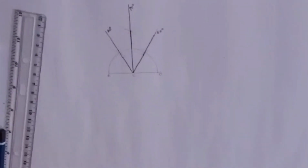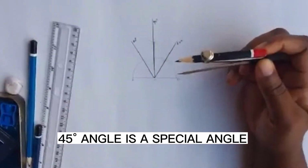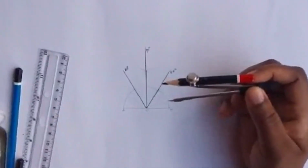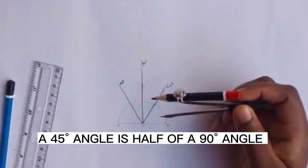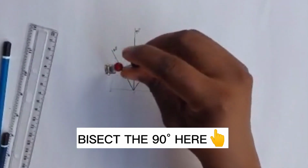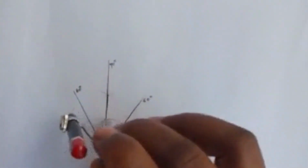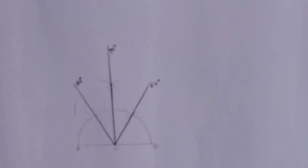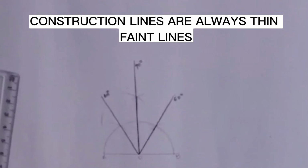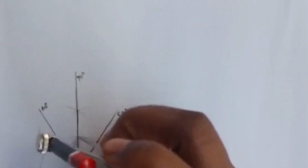Now we're also going to look at a 45-degree angle. 45-degree angle is a special angle. What's 45 degrees is half of 90. So you're going to bisect this 90 degrees here. If you notice, I'm using a lighter shade of pencil to make the arcs, because this is construction, so you can't use dark shades to do the construction lines. Construction lines are always thin lines and they are faint lines. So I'm using a very light pencil.